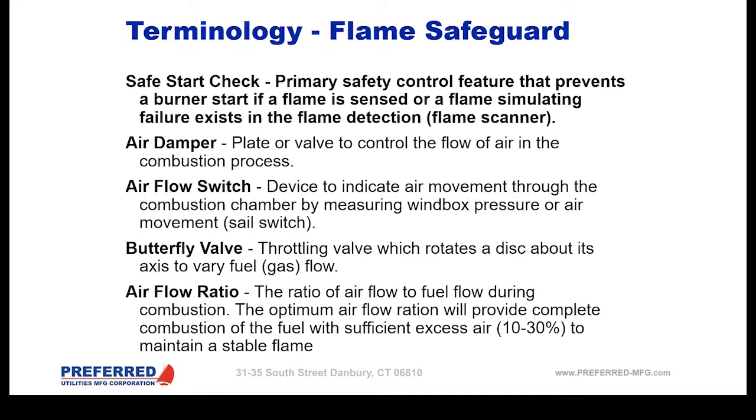Airflow switch. This is a device that indicates that there is air movement in the combustion chamber, and some will call it a sail switch. This is very important to prove that you have airflow before you go into your initial purge timing, and that way we ensure we don't have any fuel maintained in there when we light this burner off initially.